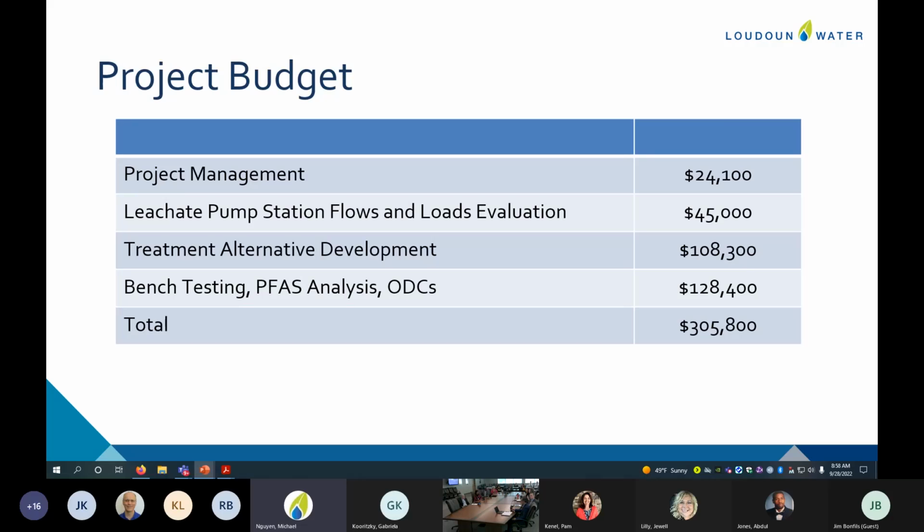because it was different by what the landfill was doing. So if we're going to build a system, we need to understand better what their future plans are for cells, and we can't just pick the 7,000 gallons because that's what they have right now. We need to make sure we're picking a design flow rate that's big enough to accommodate really all their planned forms of operation. And that takes time and study to understand.